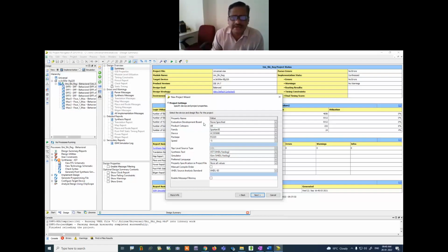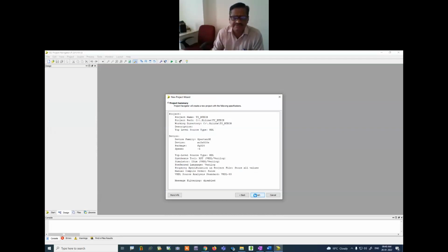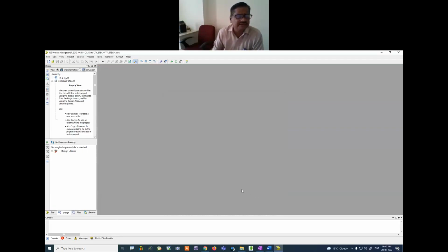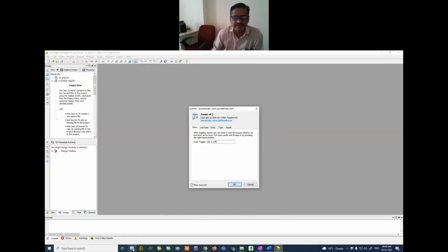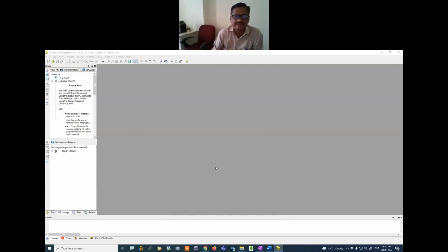Now here, click on the next, this device, Spartan 3E or whatever we wish. We can change this device later on. I will not discuss the selection of the device right now. I will click on next and finish. Now when I click on finish, look at this place. If you are not able to understand, just raise your hand. I will be in a position to explain these steps once again.